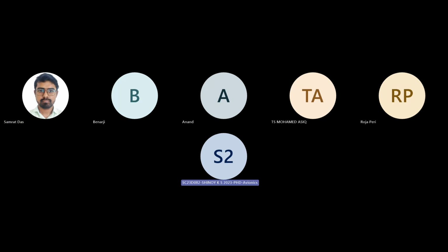Actually, sir, in the squirrel cage induction machine, the current will be there in the bars, and as you suggested, each bar will be offset by 360 by n into p by 2. So, how is the amplitude of current determined?